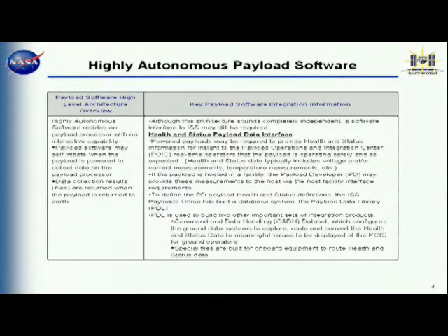If you are required to provide the health and status data, it typically includes things like current or voltage to your hardware, any sort of temperature measurements or fan speeds, information about the physical components within your hardware to make sure it's operating within nominal ranges.